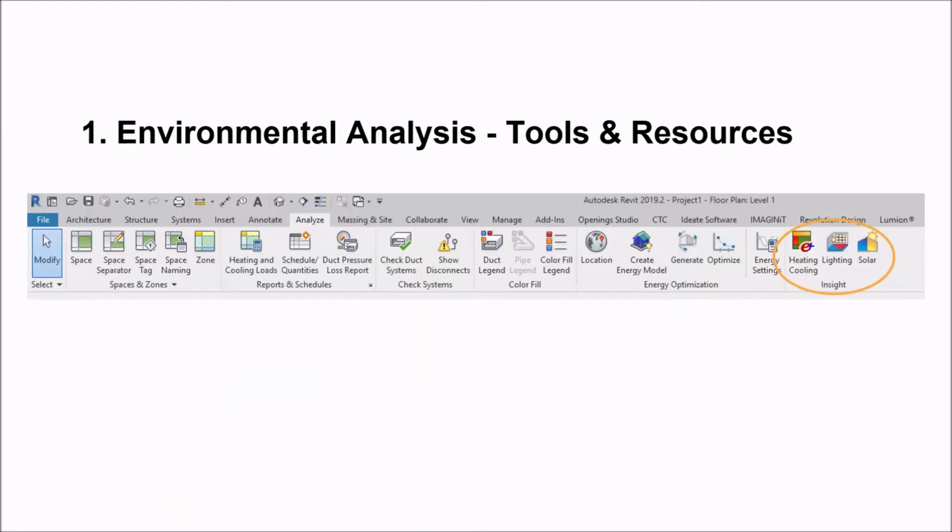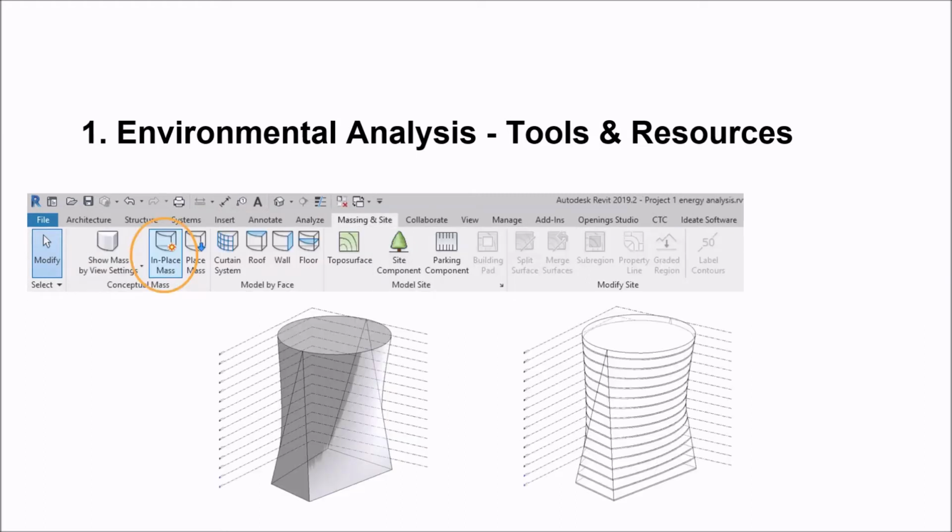Great. Now that we have Insight installed, you should see the Insight features under the Analyze tab, as you can see here in this image. Heating and cooling, lighting, and solar analysis functions are now available to us. Those tools can be used at a variety of stages of development, from concept design to SD, DD, etc. They are, of course, most impactful earliest in the design process,